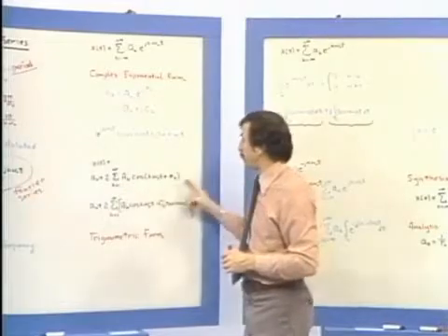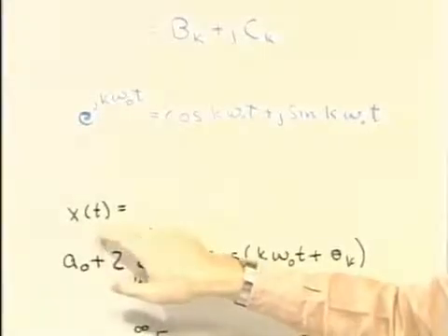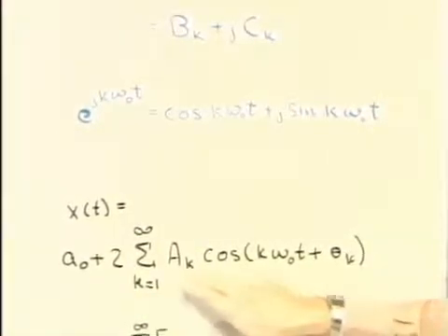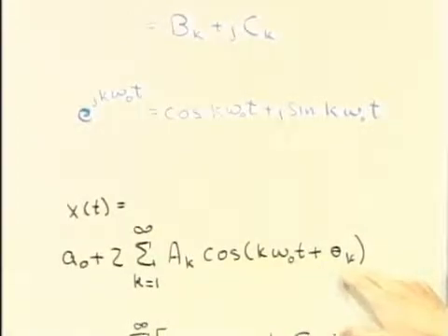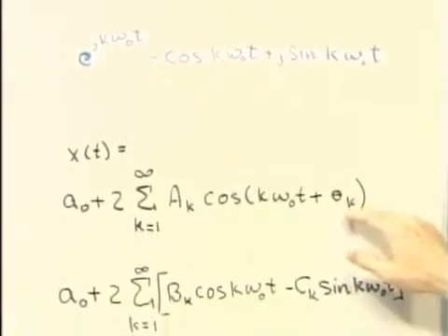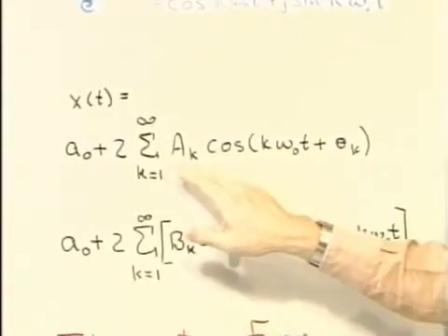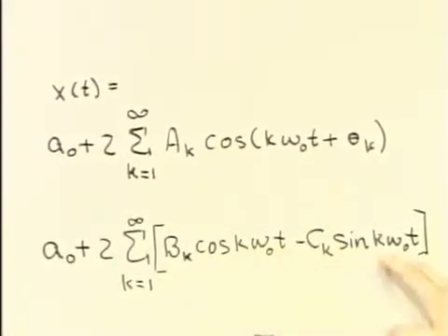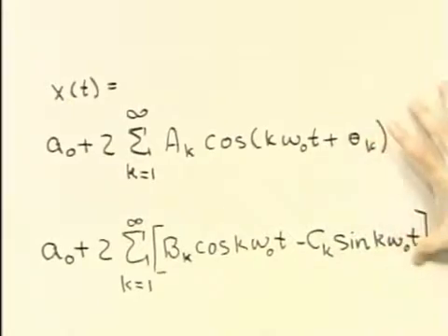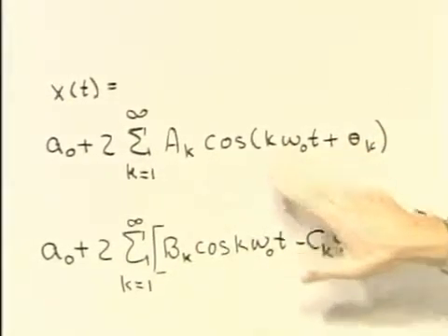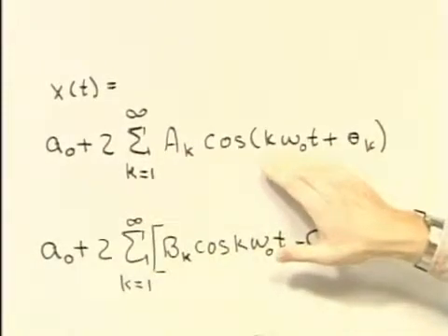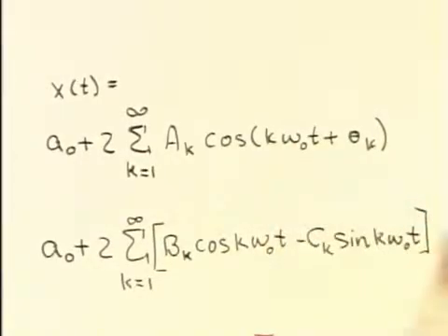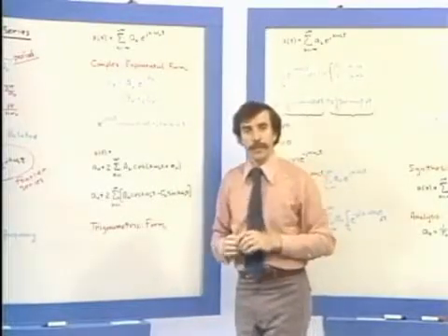a re-expression of the Fourier series expression that we had previously, either in the form that I indicate here, where now the periodic signal is expressed in terms of a summation of cosines with appropriate amplitude and phase, or another equivalent trigonometric form involving rearranging this in terms of a combination of cosines and sines. Now, in this representation, the frequencies of the sinusoids vary only over positive frequencies. And typically, one thinks of periodic signals as having positive frequencies associated with them.